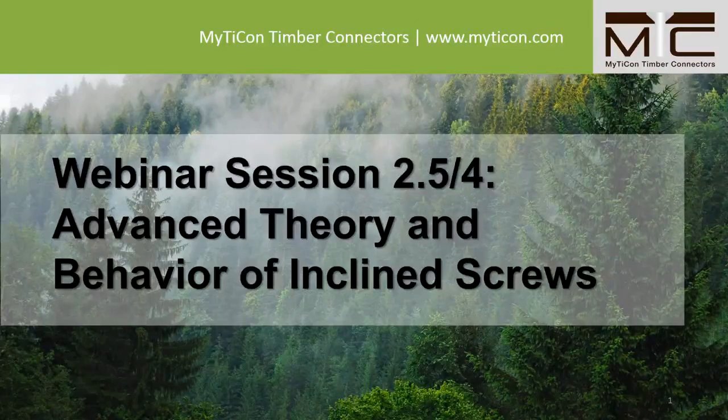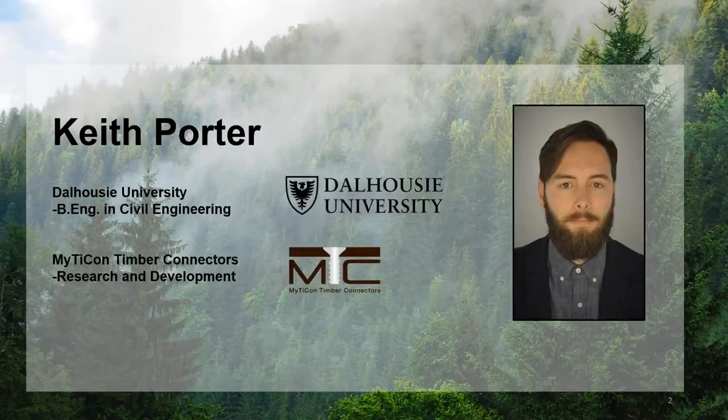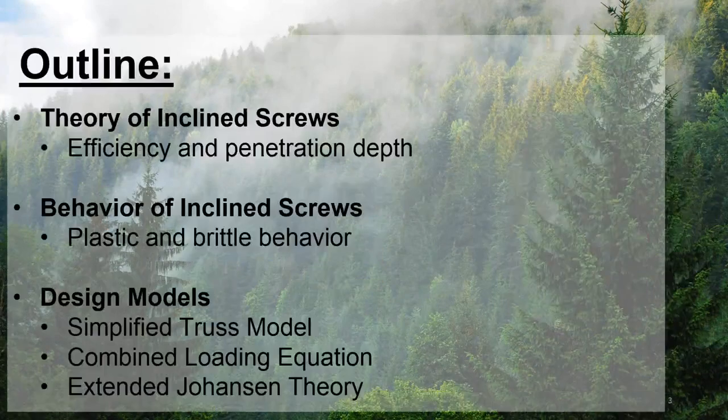So the topic today is the advanced theory and behavior of inclined screws. Once again, my name is Keith Porter, and I'm part of the technical support team here at MightyCon Timber Connectors. This webinar is intended to be a follow-up to the basic theory and behavior of inclined screws. In the basic webinar, we looked at the simplified truss design model, which considered only the axial effects of the fastener. Today, we're going to look at other design models that consider dowel effects as well.